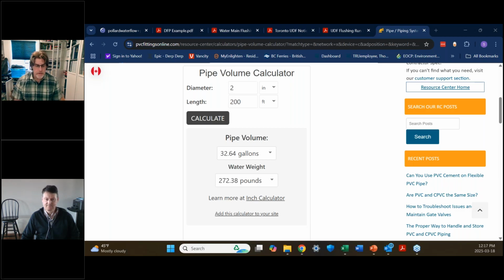David, good question. No. That may help you, but it is not going to solve all your problems. Especially in your case here, with the adhered manganese that has stained the edges and sides of your pipe. In those cases, you would have to look at some sort of pigging or swabbing to really scour the sides of that pipe.